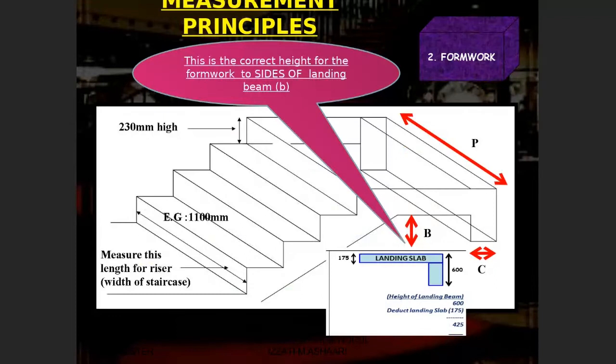Okay, I start with the riser. This is number one. Remember, you have to identify the thickness or the height of the riser. Then you have to write down the category, either not exceeding 250 or exceeding 250, not exceeding 500. Okay, you have to scale first. The answer is the length or the width of the staircase times the number of steps.